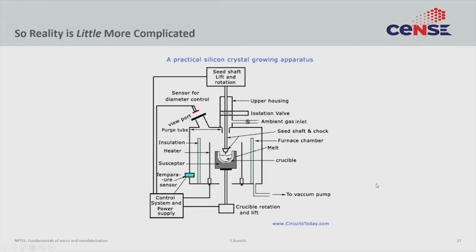Moving on. Of course, reality is always a little more complicated than the simple 1D model that I just discussed with you. Here is what an actual crystal growth system looks like. I will just highlight some of the important features. Number one, you notice the seed and the shaft lift and rotation.